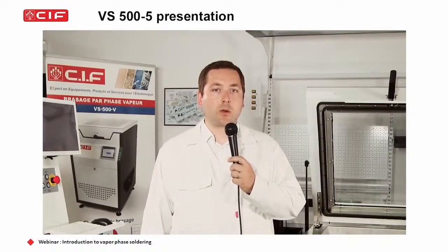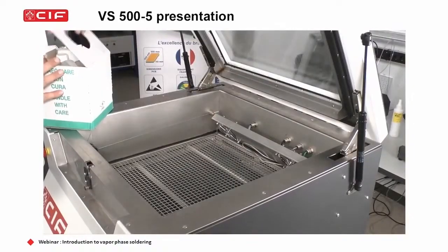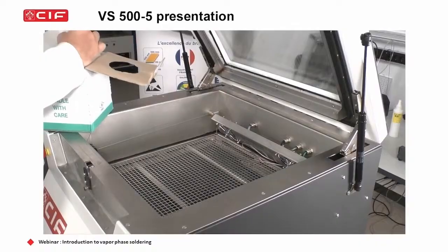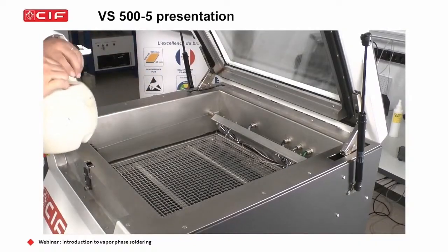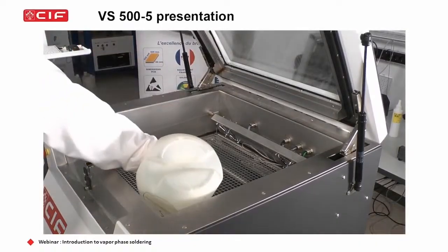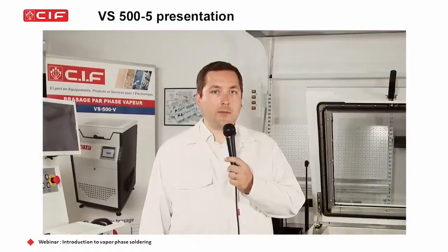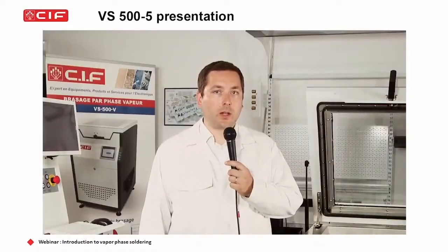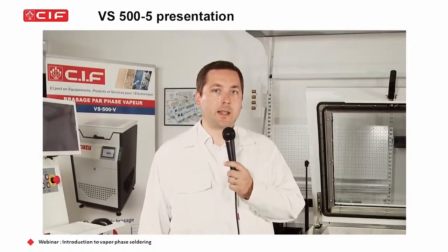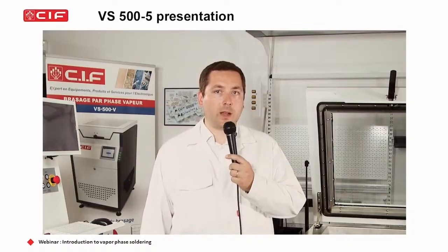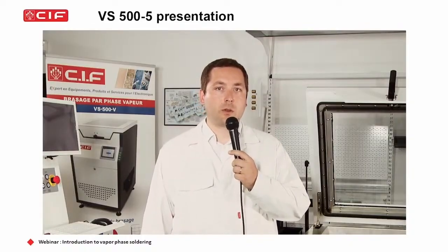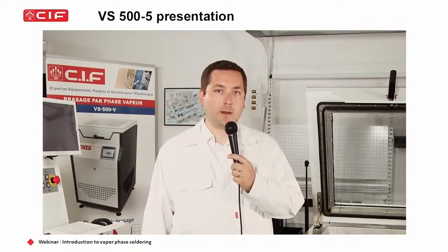It just requires a power supply to be connected to the machine, of course, and you just fill it with Galden, and then you can simply run it. The device is composed of a lid with a very large ESD safe window, which gives the operator the ability to see the process directly.